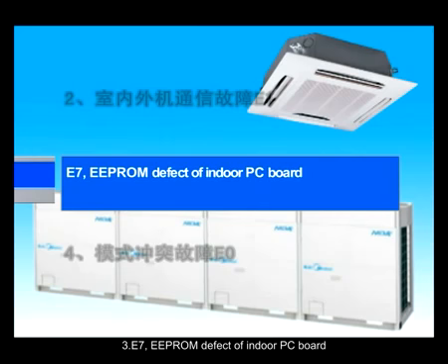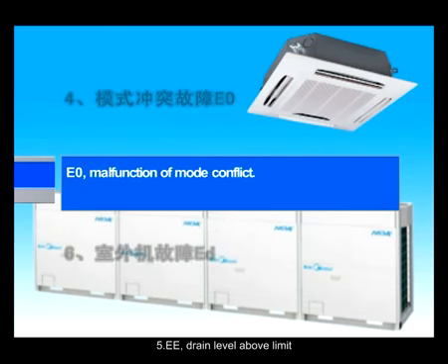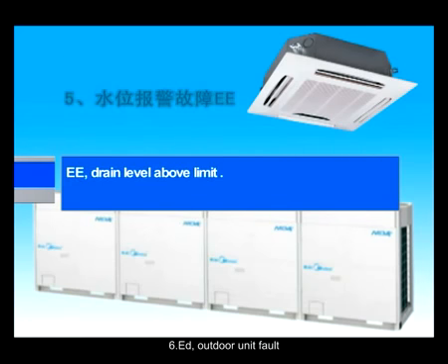3. E7, EEPROM, defect of indoor PC board. 4. E0, malfunction of mode conflict. 5. EE, drain level above limit. 6. ED, outdoor unit fault.